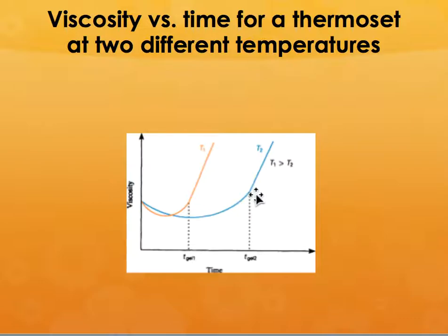Now, that will also depend upon the type of thermoset matrix. Different thermoset matrices are different; the curing temperature or the curing profile is defined by the manufacturer, and they sometimes tell you, you apply this at this temperature, you have say 30 minutes, but if you go to a higher temperature, you may have only 5 or 10 minutes. So it depends upon what the manufacturer has suggested.